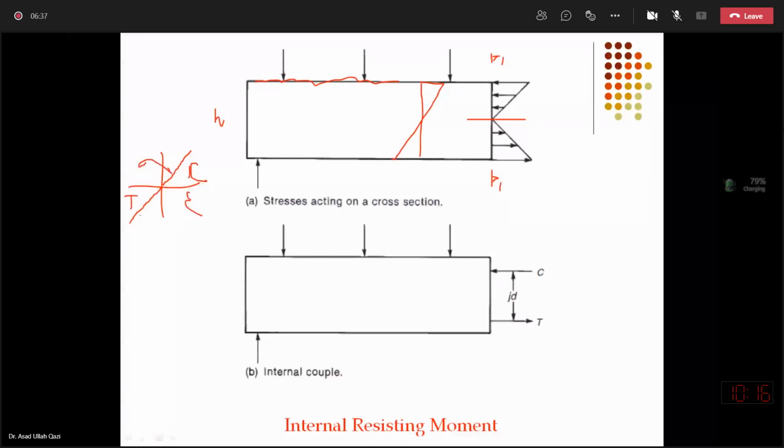such a classical material is steel. Steel has the same stress-strain behavior in tension and compression, and the modulus of elasticity is also the same in tension and compression. So the farthest fibers are at maximum strain and corresponding stress. So linear stress variation with respect to the neutral axis is obvious.